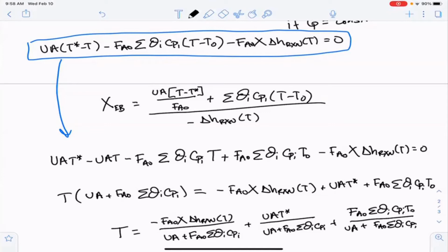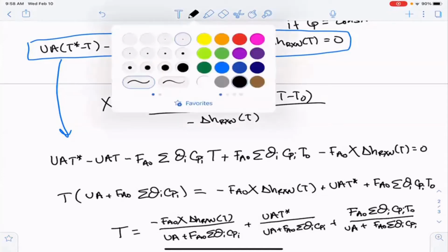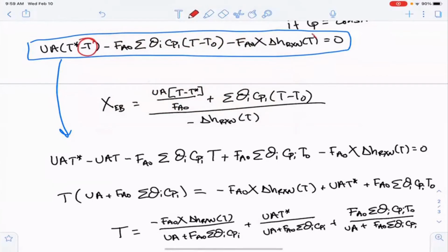And then you will have that temperature be something that is adjusted in the solver, whether that's in Excel or in MATLAB. So that's a great question. And it's another reason why it's much easier to solve something like this, because then you have supporting equations that calculate the heats of formation as a function of the temperature.